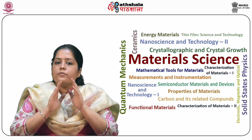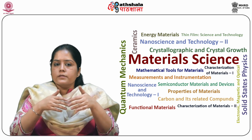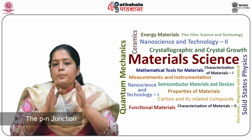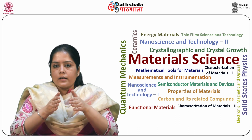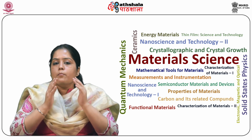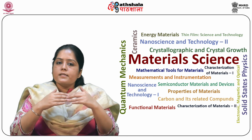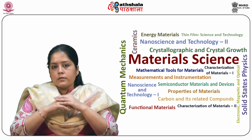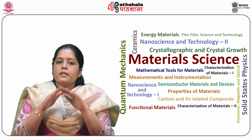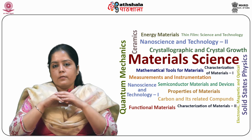The design of the silicon junction solar cell has evolved from the following characterizations. The PN junction has to lie close to the surface of the cell to give maximum current output. The excessive dopant concentration introduces effects that cause the electronic properties to be less than optimal.